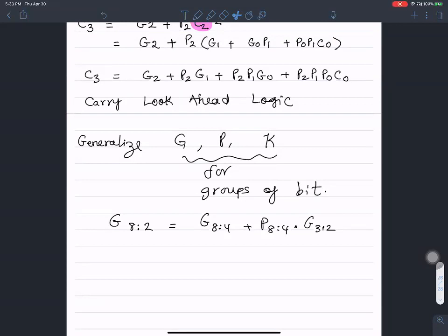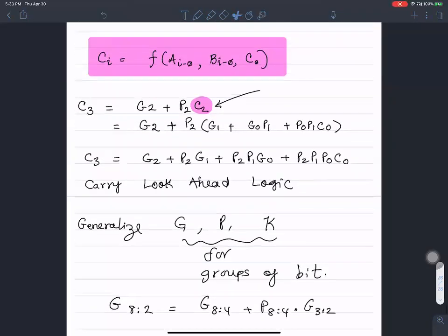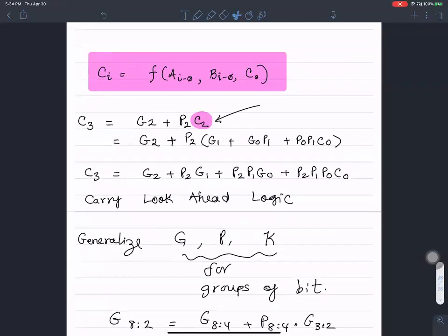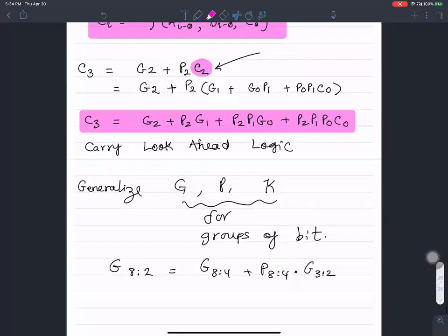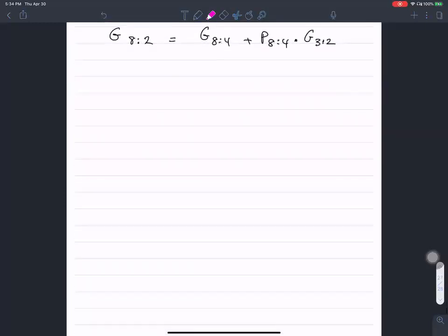And then there's a whole theory behind how you can do that. But we'll not dwell too much on it. Okay, I have given you a pretty good introduction to carry look ahead logic, which generates the carry independent of the previous stage carries. That's the idea of carry look ahead, and we leave it there. We move on to talking about other arithmetic circuits like 1 and 0 detectors, so on and so forth. So let's start with comparator circuits in the first place. Questions so far, please.